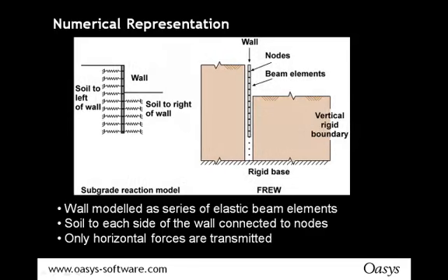For the numerical representation, the wall is modelled as a series of elastic beam elements. The soil to each side of the wall is connected to nodes, and only horizontal forces are transmitted. So in effect, it is basically a soil structural interaction analysis.